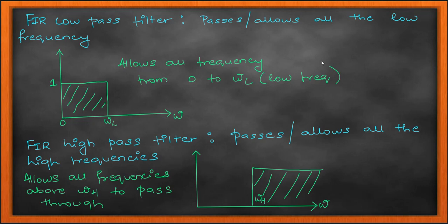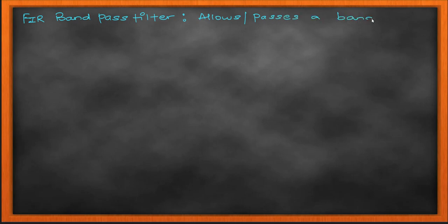Got it? So high pass filters and low pass filters are very useful. Most of the time you can use a high pass filter to extract the high frequencies. There are many applications, like flicker removal and jitter removal, because jitters, flickers and spikes that you see are going to have a strong frequency component, coming in the higher frequency band. So an HPF will allow you to pass that and keep the rest, and it is considered a filtering mechanism.